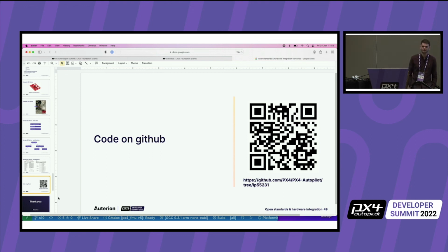That's the only thing we've so far done over Ethernet. I don't think there are any drivers for any specific kind of modules yet in PX4, but the structure would be similar. You would add a driver in the drivers folder, and that driver in the initialization would then try to open a socket and negotiate something specific.